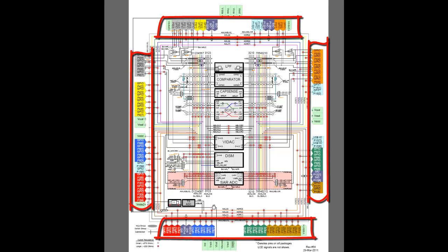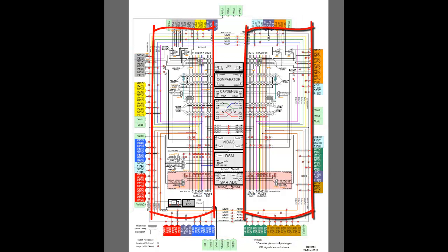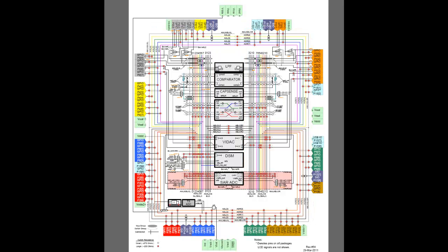Around the outside you will find all the possible pins for the largest members of the PSoC3 and 5 devices. The smaller parts contain a subset of these pins. In the center are the analog blocks. Everything in between is a routing matrix consisting of analog buses and switches to interconnect the GPIOs and the analog blocks. There are a total of 26 analog buses and numerous dedicated routes between certain blocks to the GPIO pins.